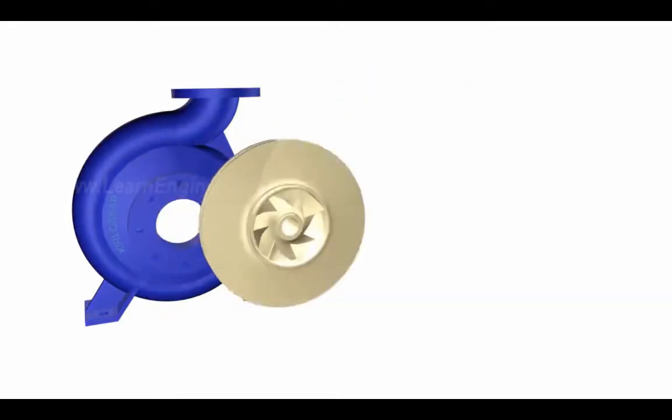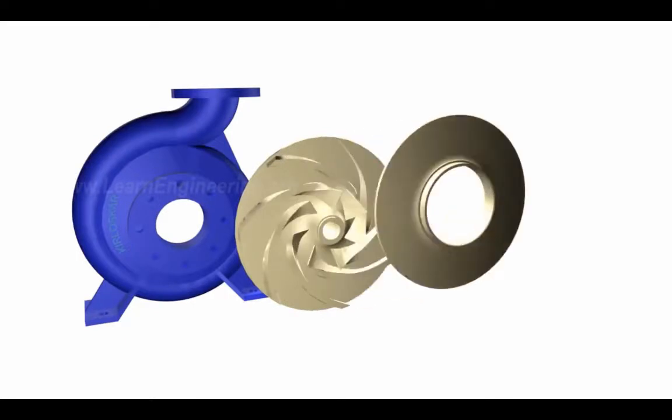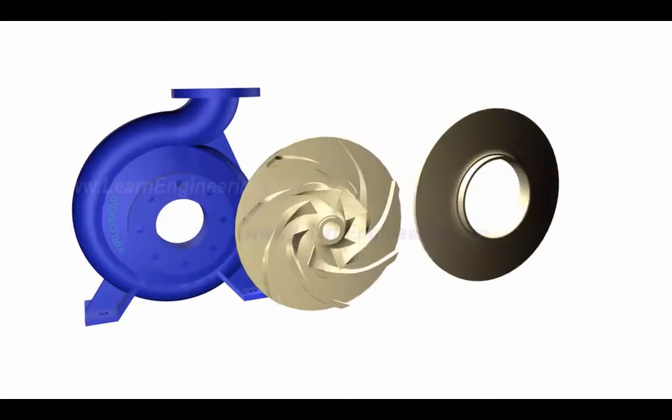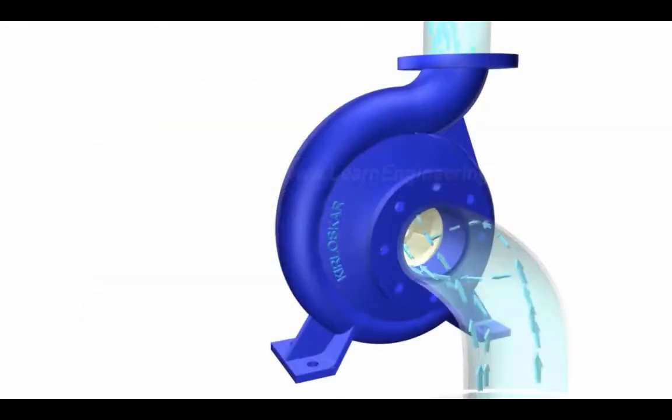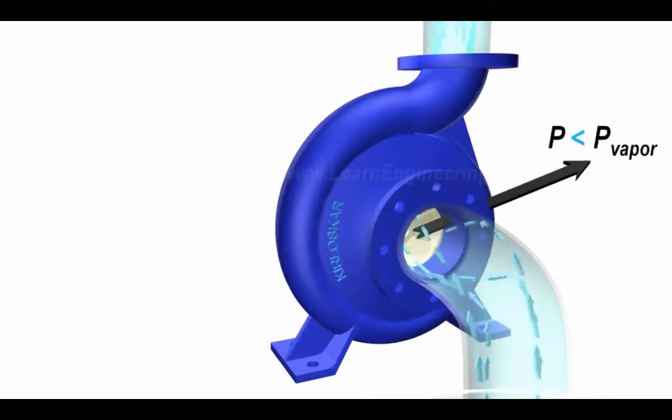Here you can see more details of vanes inside impeller. They are backward curved vanes with state-of-the-art eye configuration. This vane is extracted from a Kirloskar pump model. If pressure at suction side of impeller goes below vapor pressure of water, a dangerous phenomenon could happen.